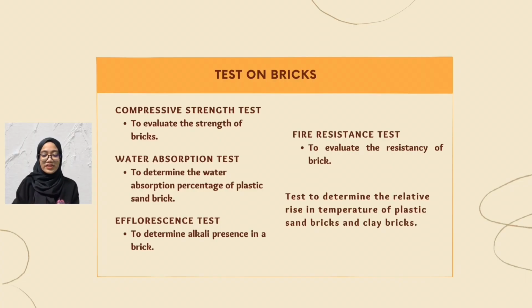This is the list of tests that researchers performed on the bricks. First is the compressive strength test, which is to evaluate the strength of the bricks. Then the water absorption test, to determine the water absorption percentage of plastic sand bricks. Third, the efflorescence test, which is to determine the presence of alkali in the bricks.